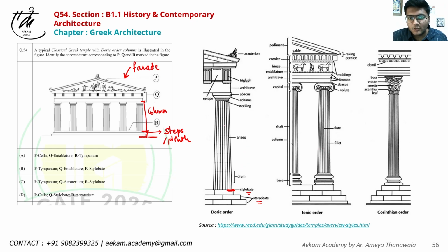Okay, so if you see in Doric orders, we don't have a base, but in Ionic and Corinthian order, there is a base. Then this is the shaft, and then this is the capital. So in Corinthian order, we have acanthus leaf capitals. In Ionic order, we have volute leaf capitals. And a very important property that has been followed here is this tapering, or in some columns there is this bulging, which is called as entasis. Very important property which helps in visual correction of perspective when viewed.